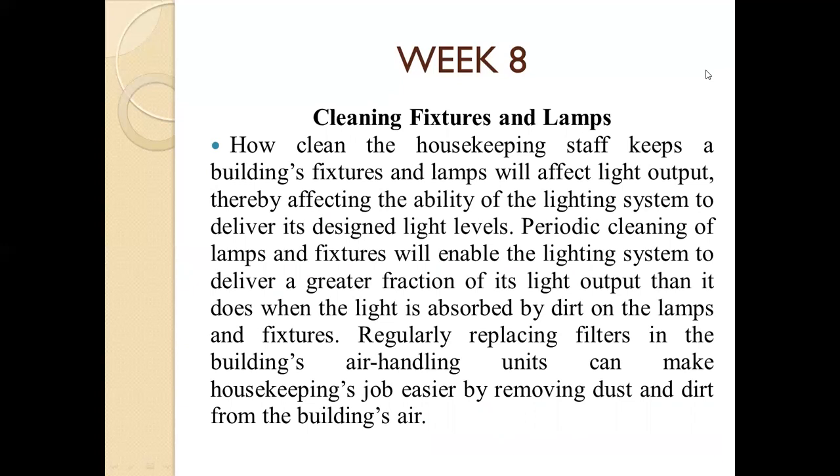Periodic cleaning of lamps and fixtures will enable the lighting system to deliver a greater fraction of its light output than it does when the light is absorbed by dirt on the lamps and fixtures. Regularly replacing filters in the building's air handling units can make housekeeping's job easier by removing dust and dirt from the building's air as well.